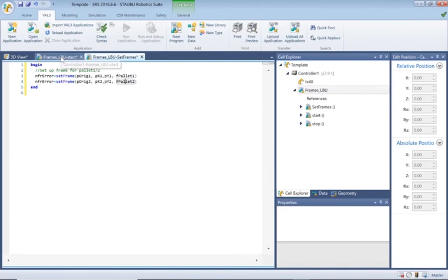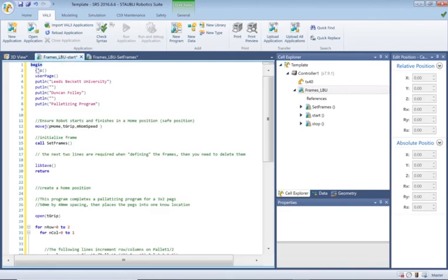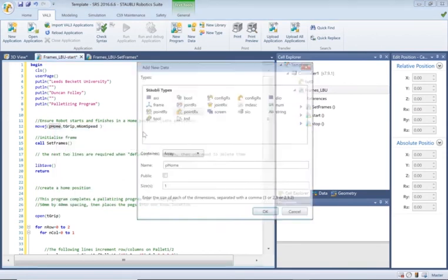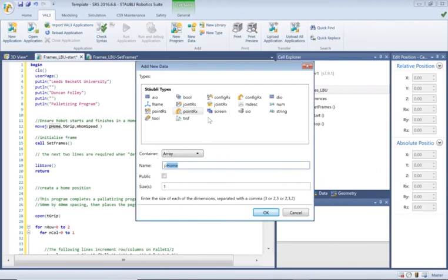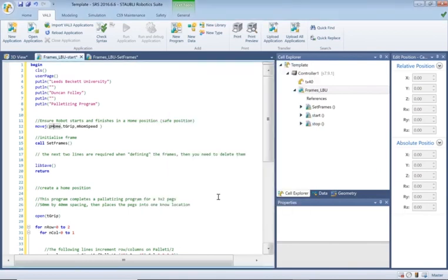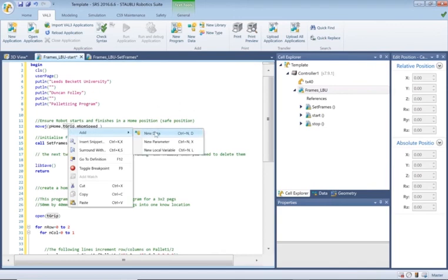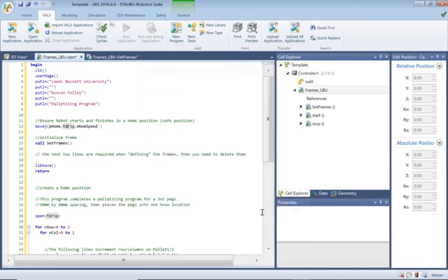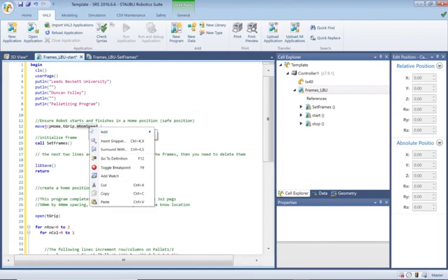Okay, let's go to the main program now. So it's clear the screen and print whatever you want on the screen. It's up to you. We've got a joint mode here, so it's right click. This is a safe place for the robot. I'm going to pick joint RX for that one. This is a gripper name. We'll need to define that in a little while, what the offset value for the gripper is. So that is a tool. Yeah, that's correct. And this is the motion descriptor.